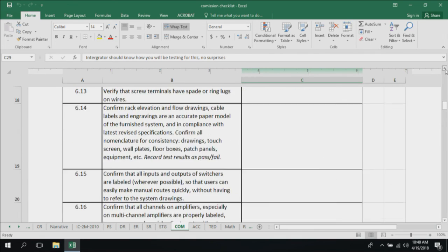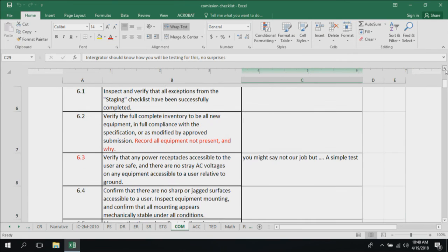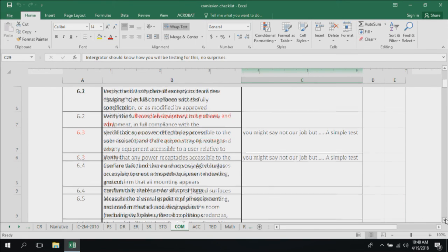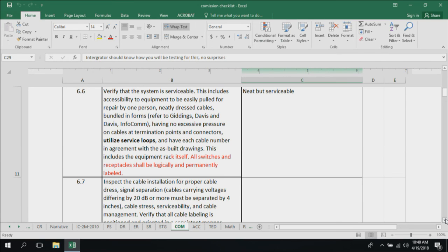And then just some little things I've taken to carrying with me whenever I go out to a new install. Those little inexpensive outlet checkers you can get at Home Depot for, I don't know, $10. Use those. Try it. Just plug it in.